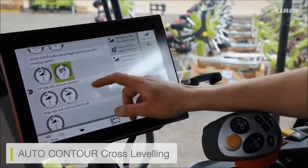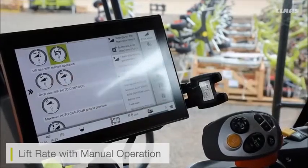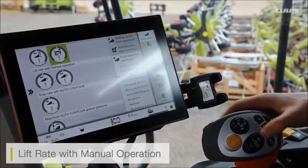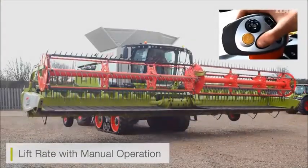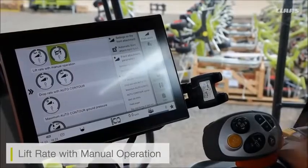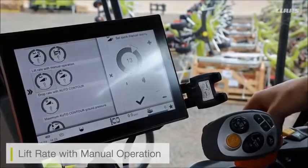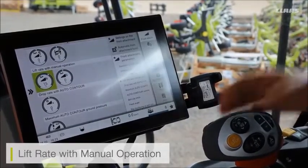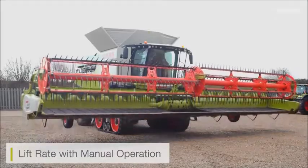Below this setting, I can also see my lift rate with manual operation. This is the percentage of lift rate when I'm manually lifting and lowering my main cutter bar. If I increase the lift rate, so increase this percentage to maybe 10 or 15, when I then lift my cutter bar manually, I'm going to have a faster lift rate on the cutter bar itself.